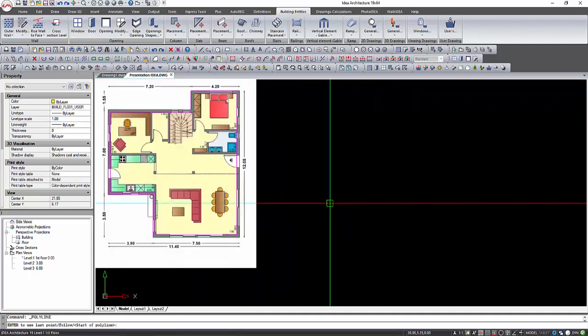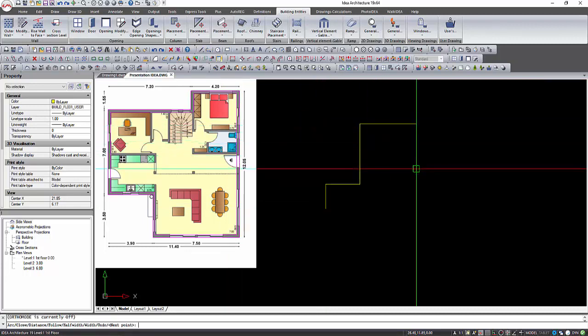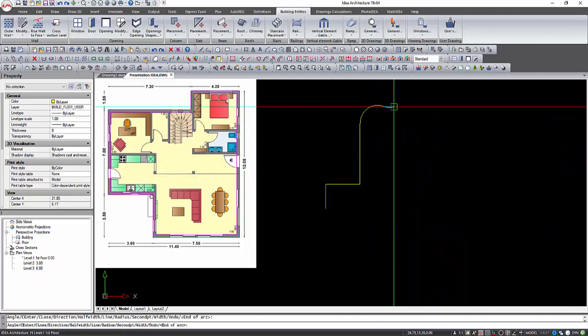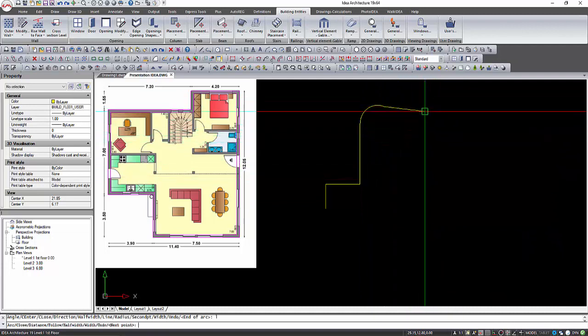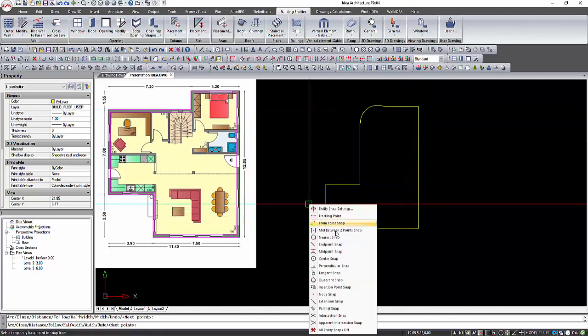In IDEA we are able to design a wall from a simple polyline. Almost all the BIM entities can be created from a simple polyline, and this is something that we will see many times in this demo. Here, I create a polyline, with an arc segment and some linear segments. This polyline could be the outline of a building.